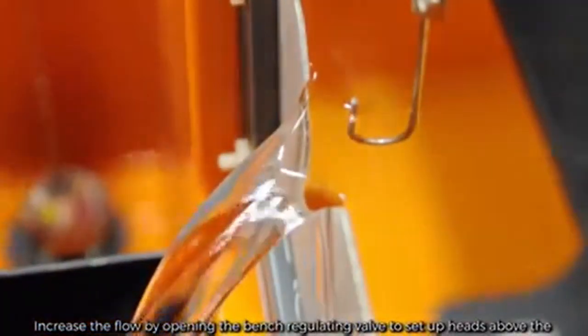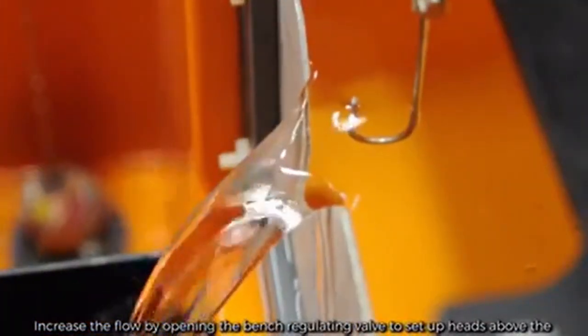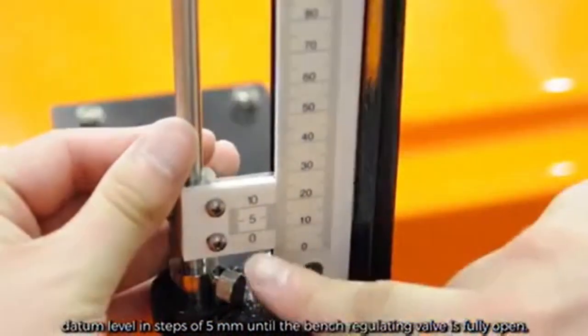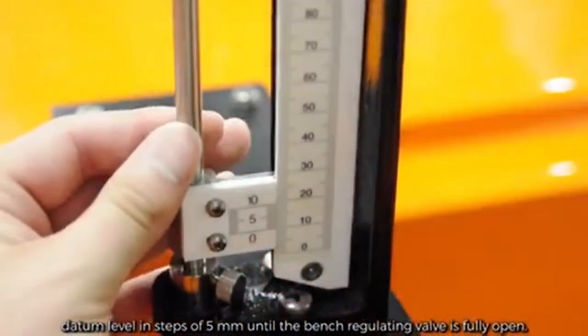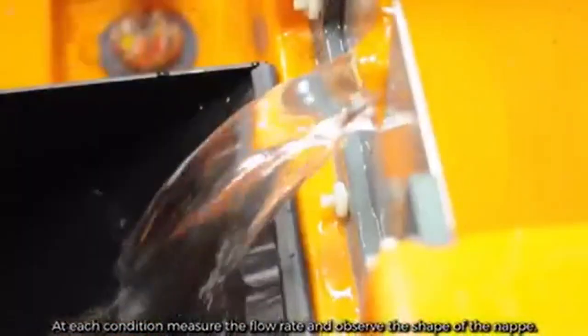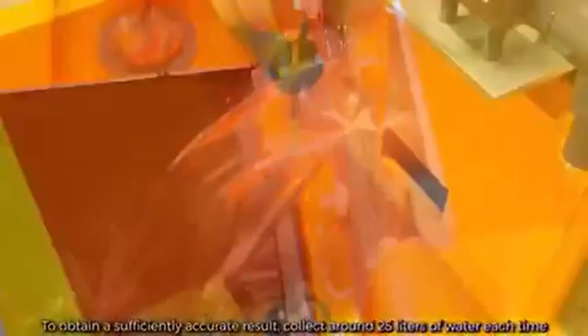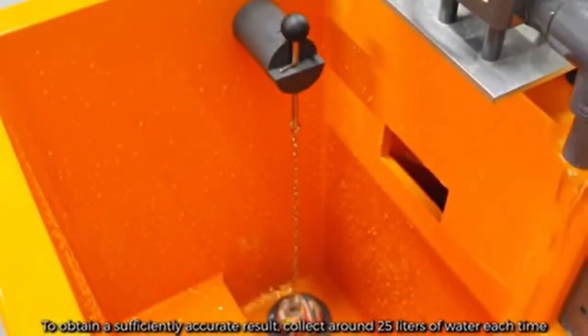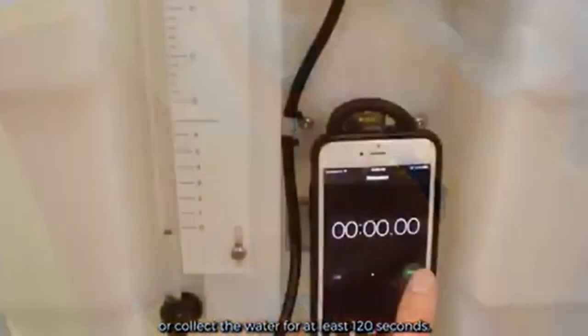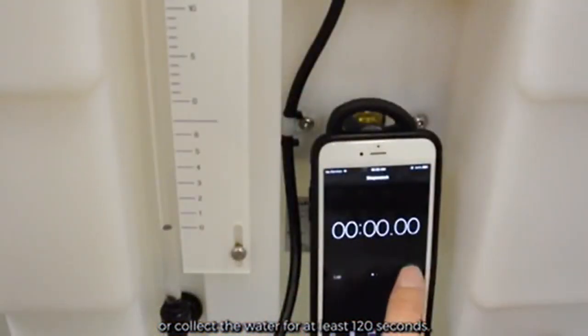Increase the flow by opening the bench regulating valve to set up heads above the datum level in steps of 5 mm until the bench regulating valve is fully open. At each condition, measure the flow rate and observe the shape of the nappe. To obtain a sufficiently accurate result, collect around 25 liters of water each time, or collect the water for at least 120 seconds.